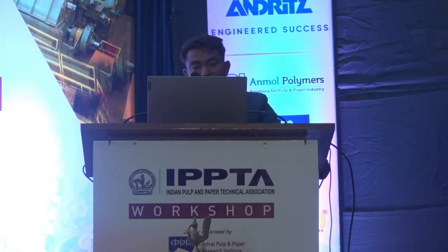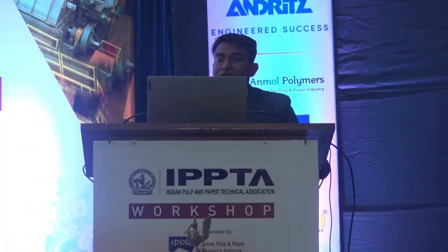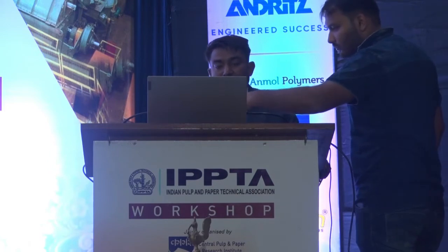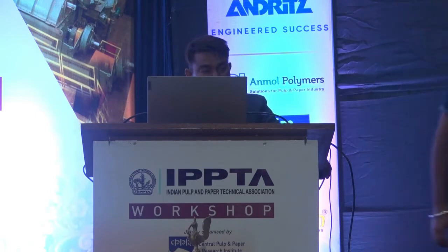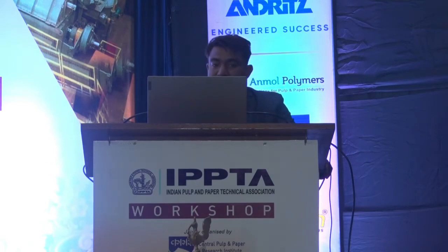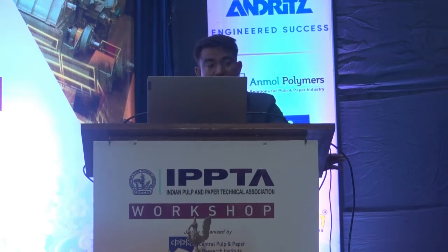Of heat transfer, mass transfer equipment, designing, fabrication, erection, commissioning. In this company, we have 3 patents. One I am representing today: a two-way feeding and condensate sealing system to increase the individual effect overall heat transfer coefficient. Increasing the individual overall heat transfer coefficient means we will increase water evaporation capacity, solid concentration, and steam economy without addition of a new body or surface condenser.